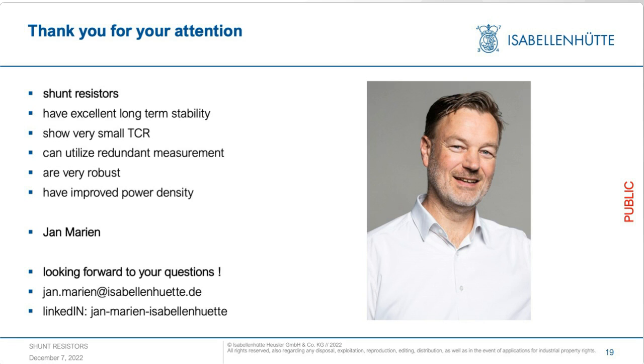And when you do the compensation at the physical level, at the shunt level, then your TCR curve becomes very flat or even close to 0. So all the measurement errors and also the time delay errors you have in your calculation become negligibly small, and the robustness of the system is much higher.